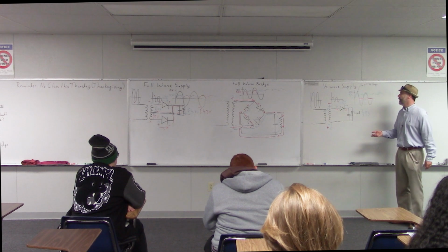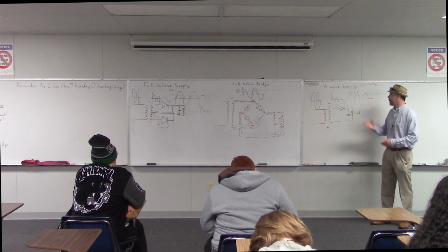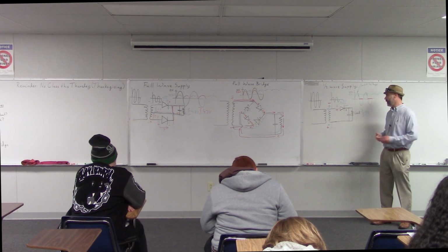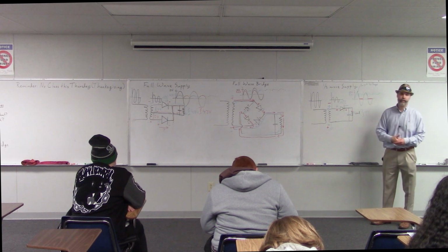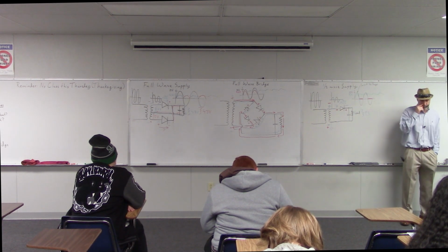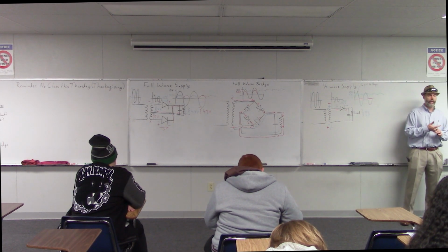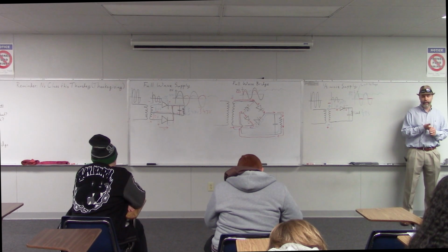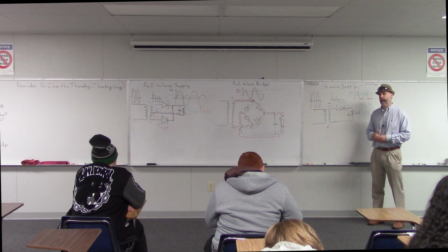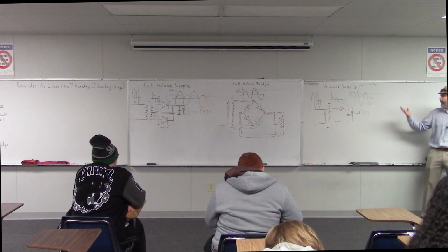So first of all, one of the advantages of the half-wave power supply is that it's really simple. It's just got one component in the rectifier, one diode, so it doesn't get much simpler than that. And simple is often a good thing. It's easy to build, it's easy to repair, and it's cheap because we only need to buy one component. So all of those things are advantages. Can anybody think of a disadvantage to the half-wave supply?